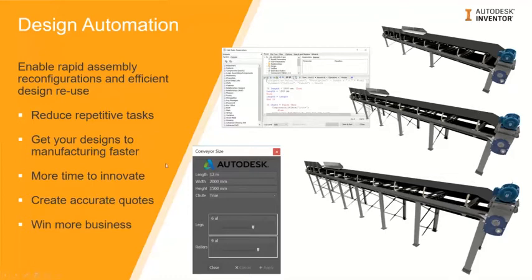By using the iLogic properties of Inventor, you can set a table wherein you can directly change the width and the height, and automatically all components included in your assembly or your conveyor will follow depending on the changes you made in our table.